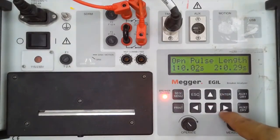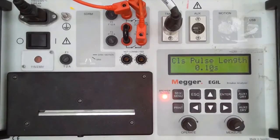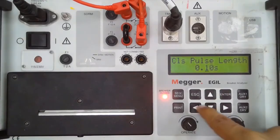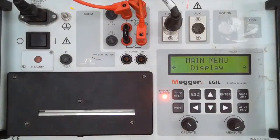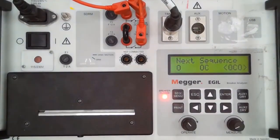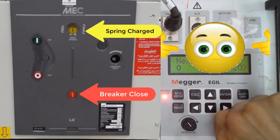We said that 20 milliseconds is quite sufficient for both the first open pulse and the second open pulse. Then, for the close pulse, we said the close pulse can also be 20 or 30 milliseconds. Now I am ready with my settings and can start executing my test. I will begin to take measurements.